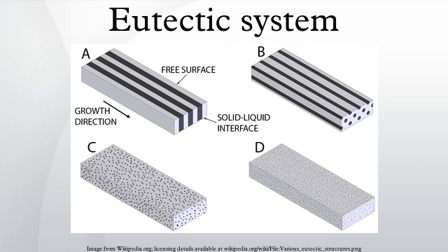Other critical points: eutectoid. When the solution above the transformation point is solid, rather than liquid, an analogous eutectoid transformation can occur. For instance, in the iron-carbon system, the austenite phase can undergo a eutectoid transformation to produce ferrite and cementite, often in lamellar structures such as pearlite and bainite. This eutectoid point occurs at 727 degrees Celsius and about 0.76% carbon.